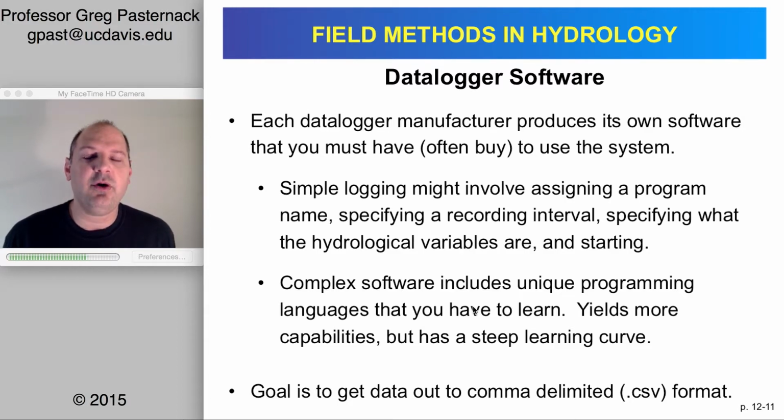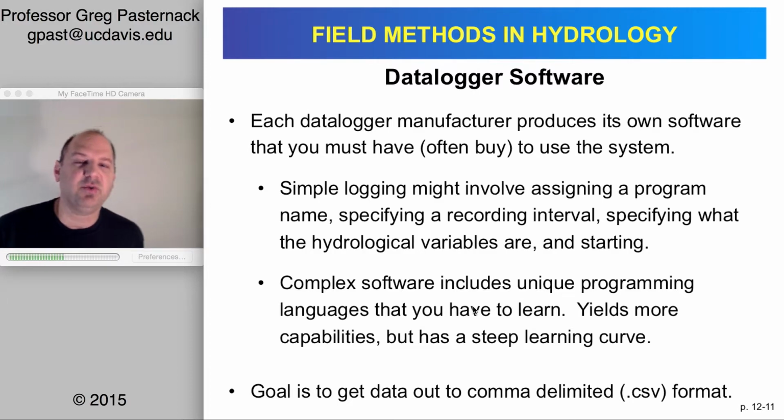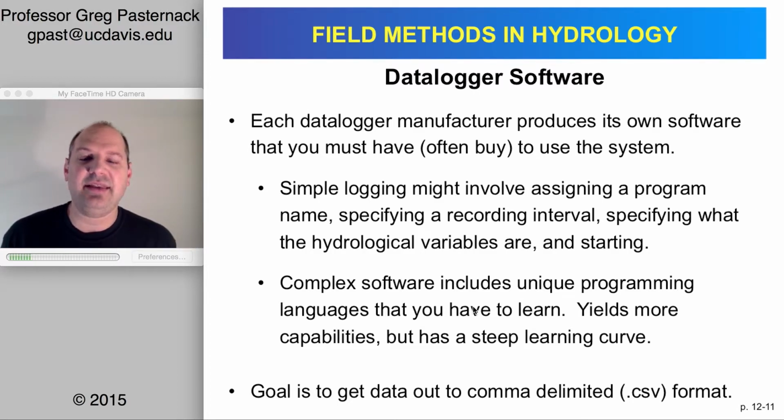Datalogger software has been changing a lot. In general, each manufacturer has a unique language for their own data logging, and that can be a little bit annoying. But most software is designed to be very user-friendly, where there's a range of sensors that goes with that data logger from that company, and they have a pre-programmed user interface that's fairly easy to use with the sensors. However, if you're bringing sensors in on an SDI-12 or some other way, then you could start to run into problems with the pre-programmed tools that are available.